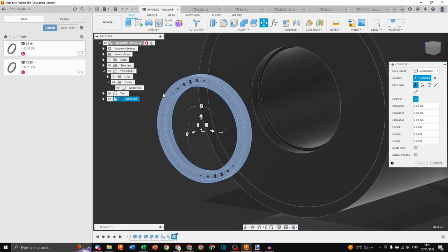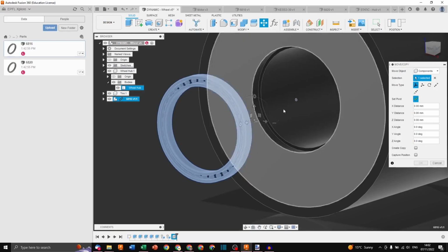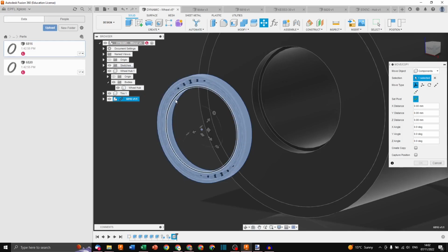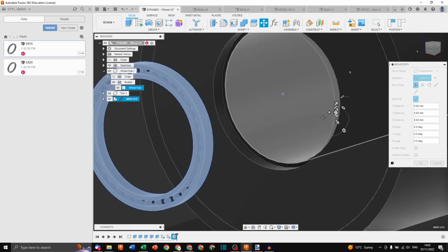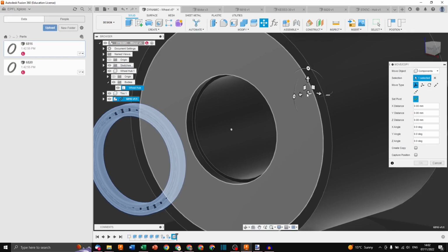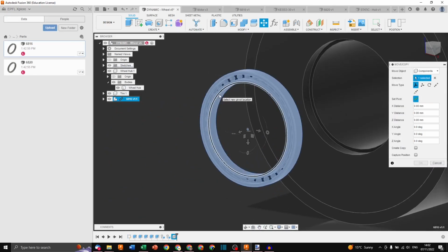If you want to select the center of a part, you press Control. If you press Control, you'll clip into centers. Right now, I have Control held down. If you press Control and click on objects like this, it automatically puts me in the center. If I just let it float, you can see my arrows have gone from dark when I press Control to light. Now it wants to go wherever it can. It's not going to go in the center. But if you want different centers, like if I want my move at the center of the wheel, I press Control. As soon as you put it down, you need to press OK.